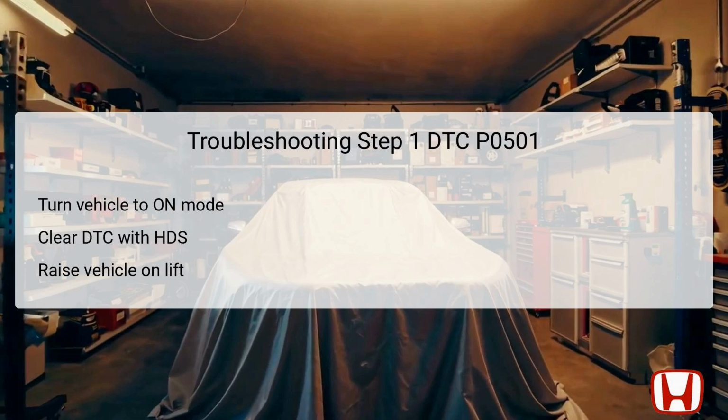The first step in troubleshooting DTC P0501 involves turning the vehicle to the on mode. This prepares the onboard diagnostic system for diagnostic tests. Next, clear the DTC using the HDS, Honda Diagnostic System, tool to reset any stored trouble codes. This action allows for fresh data to be gathered during subsequent steps.